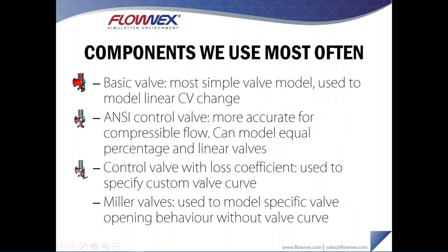All right, and lastly, we have a couple valves. The basic valve itself is the most simple valve model. This assumes a linear change in CV from 0 opening to full opening. It's probably the easiest valve to use. It'll work well for valve sizings for incompressible flows.